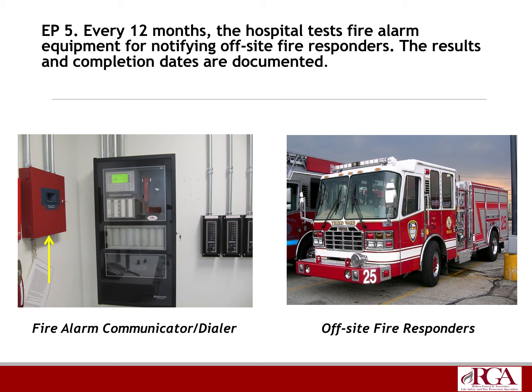And also part of this testing method is to test both phone lines for integrity or both means of transmission, as you might not necessarily have two phone lines. You could have a primary phone line and then a cellular radio as a backup, or you could have voice over IP phone line as a backup. Either way, those phone lines or means of transmission have to be checked and tested for integrity, and you have to get the 90-second timer on your three respective signals. That is your fire alarm, trouble, and supervisory.